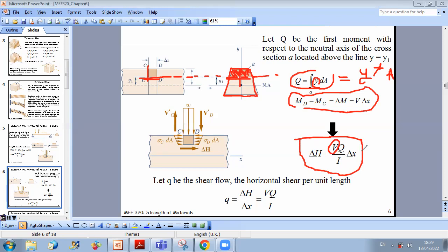And this is how we can relate the total shear force developed to the force that is parallel to the x-axis, created due to, if you want, shear along the direction parallel to the x-axis. And this will help us in the next slides to see how we relate shear stresses to V. Okay, so until now we have developed an expression for the force over a certain distance delta x. In general, we are interested in forces per unit length.